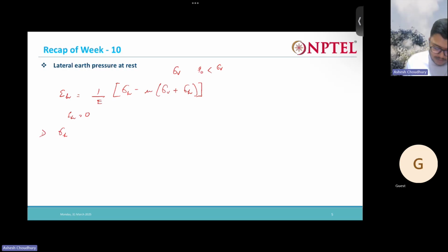So I can have sigma h equal to P naught equal to mu by 1 minus mu times sigma V.